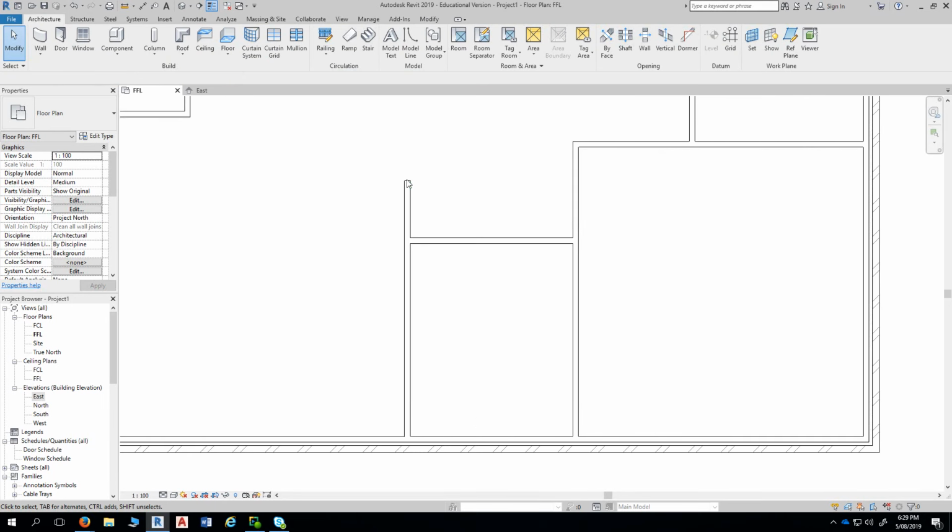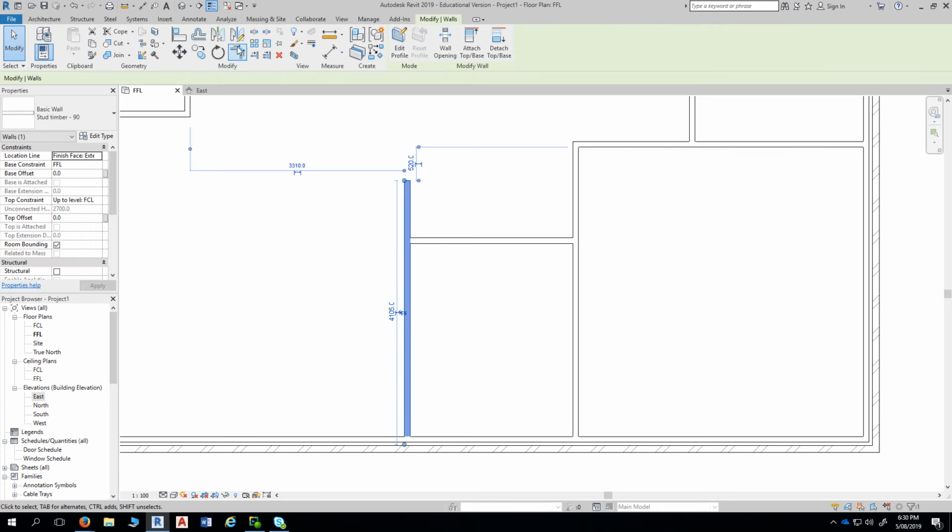Now, if the end of this wall needs to be at the same height or position as this wall face here, the obvious thing to do there is to use what? The align tool. Rather than trying to work out what that length should be from here, we know it has to line up with this wall face up here. So we use the align tool.